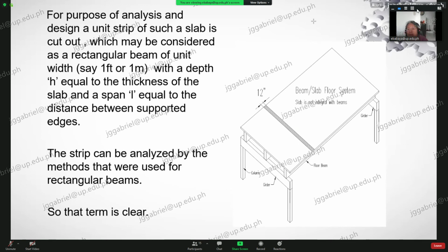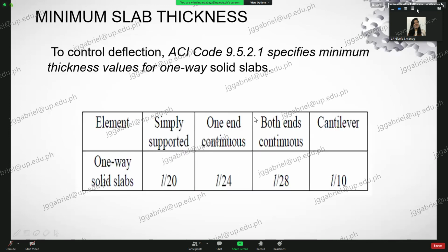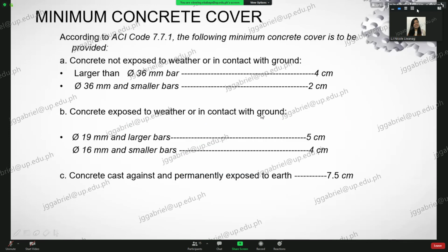Anyone? Why could that be? Sir? Yes. I think it's because after setting, the concrete still shrinks when it dries, so those bars maintain its length. Correct. That's correct.